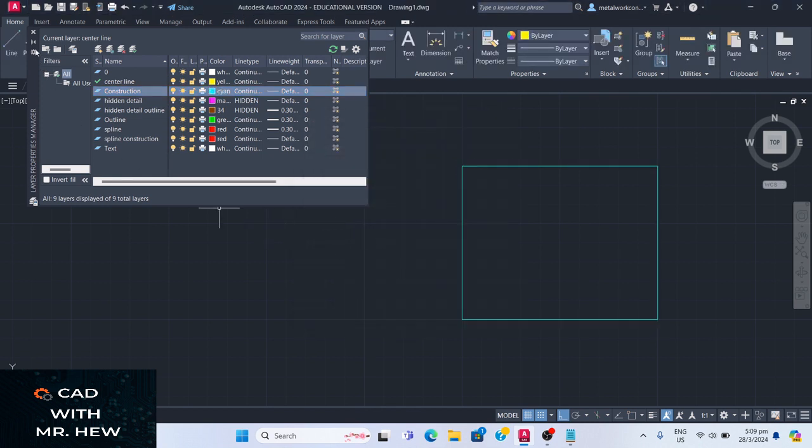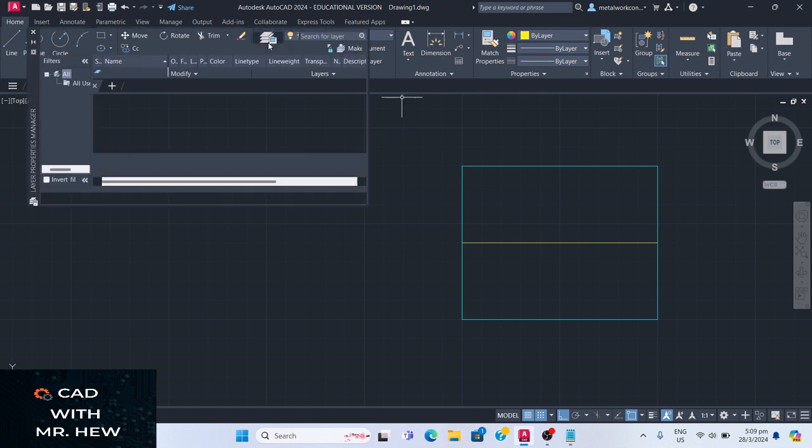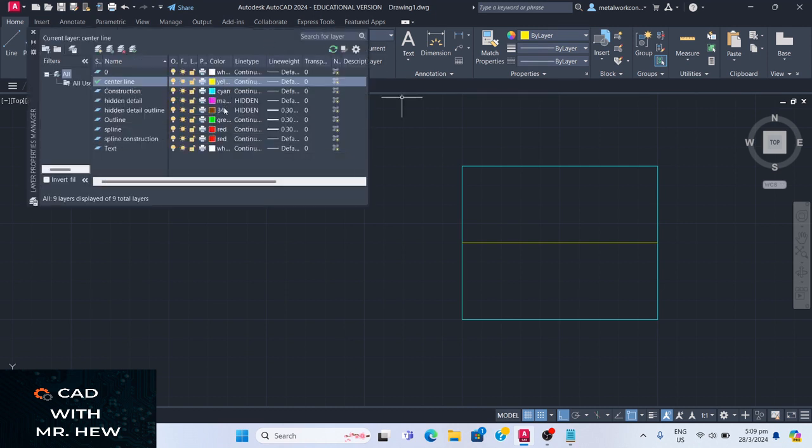All right. So we close this box now. So what I'm saying now, the center line is selected, right? If I draw a line, this is an object snap. If I turn it on, the triangle there represents the center. That's our center line. Enter. Now, you're not seeing it as a center line. So let us go back to the layer manager. This is our center line.